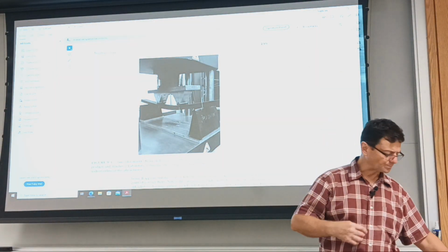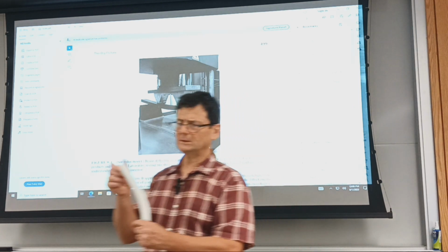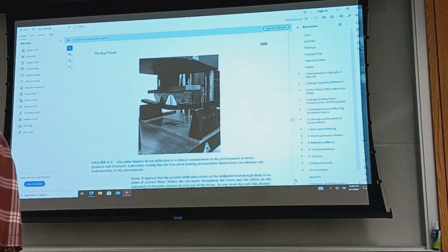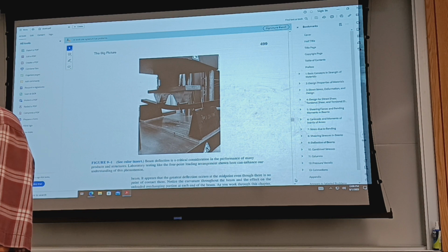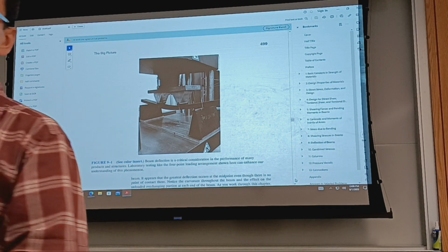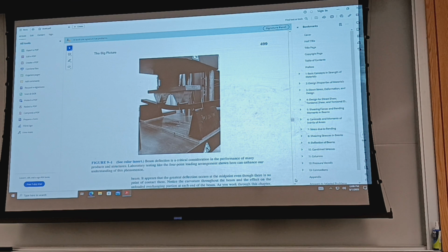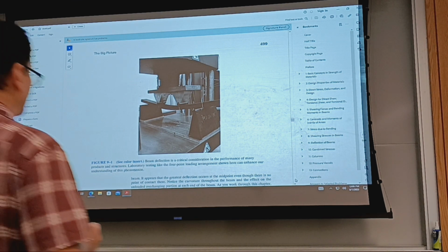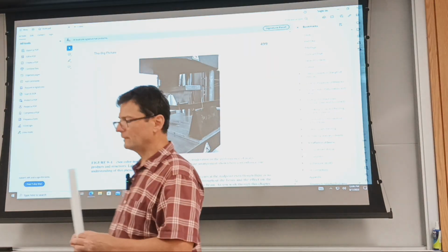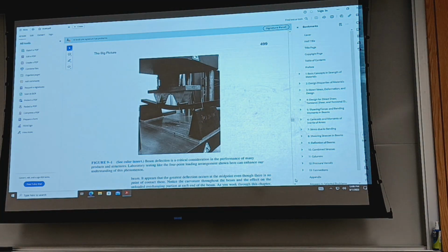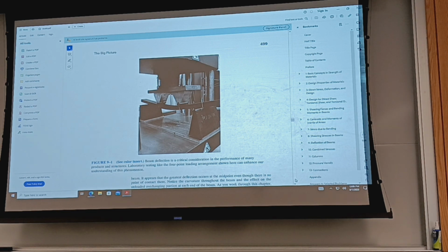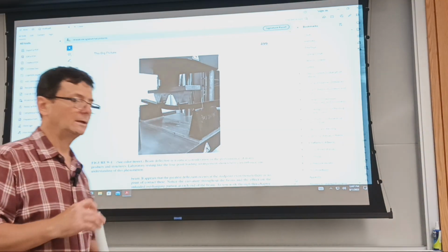You then have the very tall buildings, and under the effect of the wind, excluding earthquakes, so under the effect of wind, they can swing, right? And I think all of them now have tuned mass dampers. Okay, so wind blows, the top swings. You have your office at the 100th floor. You get seasick or motion sickness. So they are what are called tuned mass dampers.